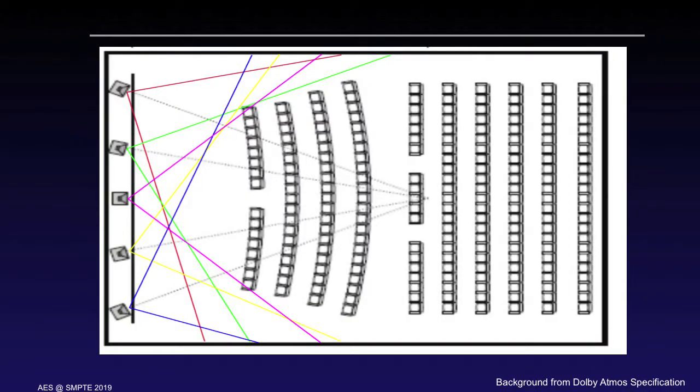Okay, so with that background, let's take a look at our initial selection here. We have 5 loudspeakers. They're aimed at the reference point. And we see that with the coverage we had there, we covered all the seats. Now, the difference in audio perspective will vary from seat to seat. Your mileage may vary here because you'll be off-axis or on-axis for different speakers at different times.